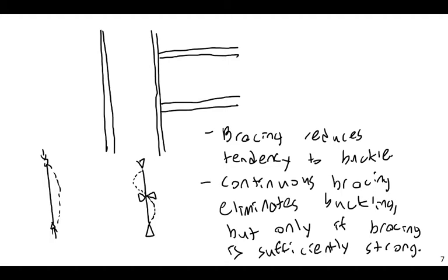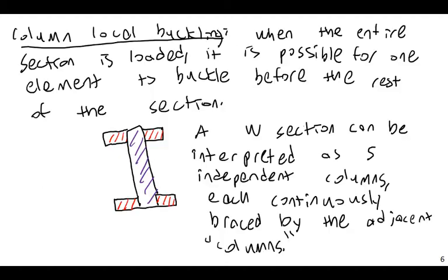And in the same way, just like a little 2x4 is not going to be able to, now again, this is not that same ratio, the internal elements of our column here are actually proportionate to each other, but there can be cases where, before you reach your ultimate load in buckling, one of the elements will fail before that. And this is really what we mean when we say a slender element.